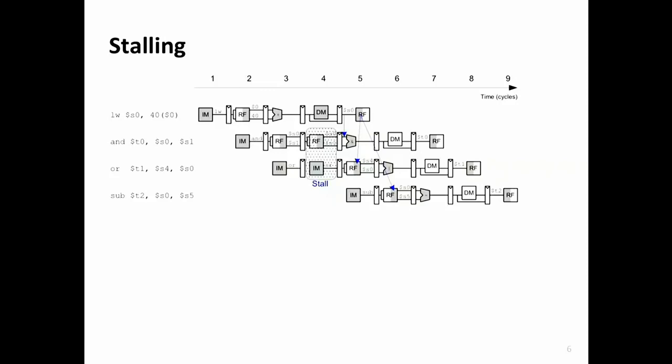I should have had the previous slide, but basically, that's impossible to do unless you extend the clock cycle. If you remember the discussion yesterday, if you extend the clock cycle, get the data from the load and supply it to the beginning of the ALU in the same cycle, that's a bad idea. Now you actually have 2x the clock cycle potentially. So in this case, we did need to stall the pipeline, stall the AND instruction, which is shown in this figure. This load generates its value, results, at the end of this memory stage and latches the result, and that result is immediately forwarded to the ALU stage such that the AND can execute, but AND has to wait for 1 cycle over here.